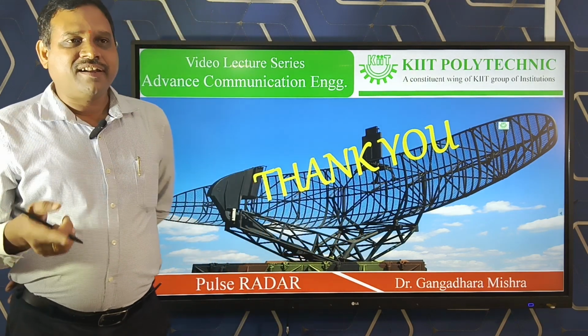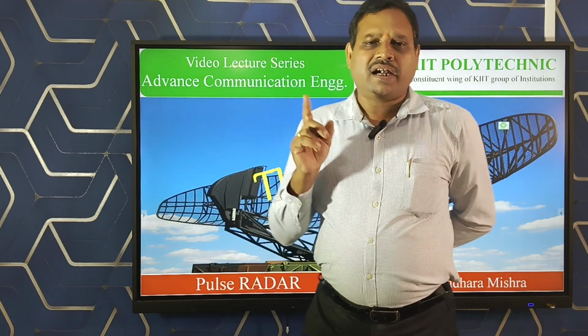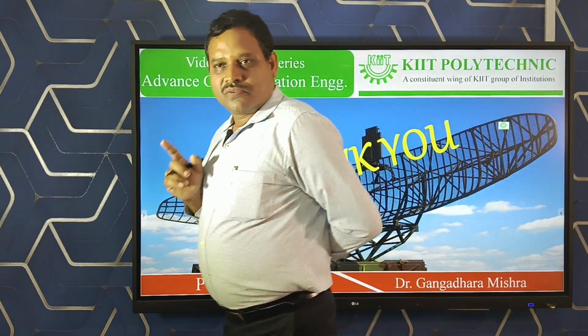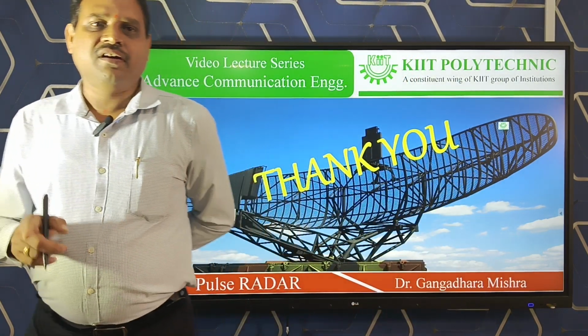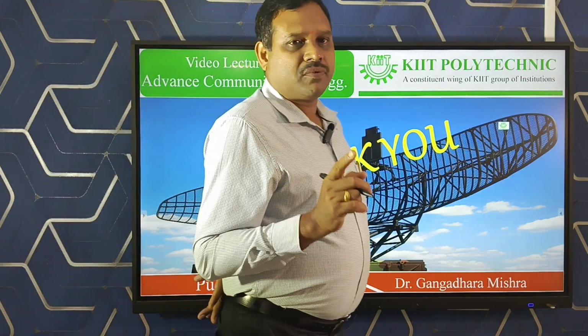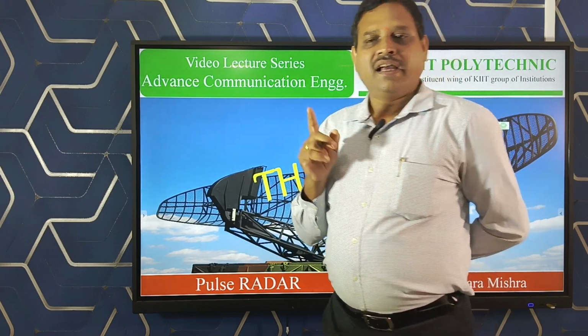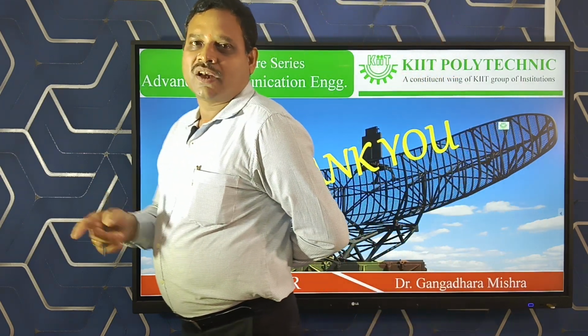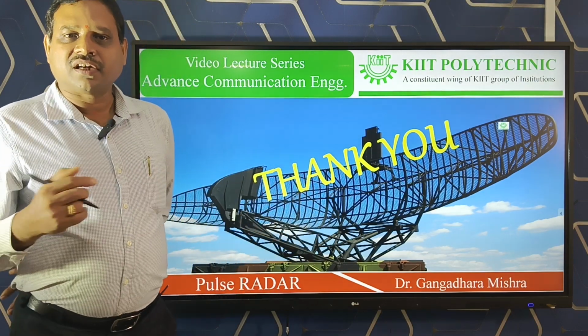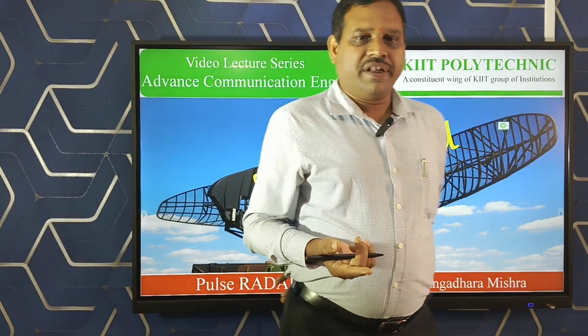And as we are synchronizing the antenna direction and the sweep direction, from that parameter we can find the target positional value, that is the bearing information, and in some cases, if we are using a third coordinate, we can also measure the elevation coordinate.